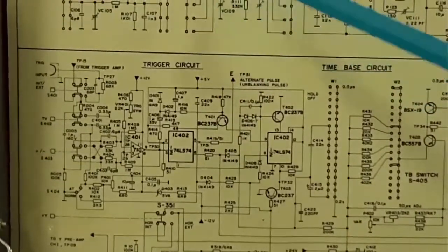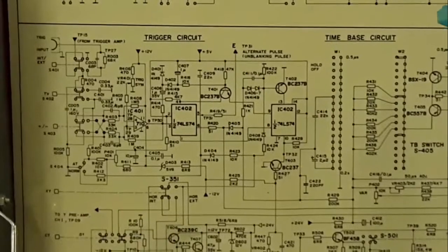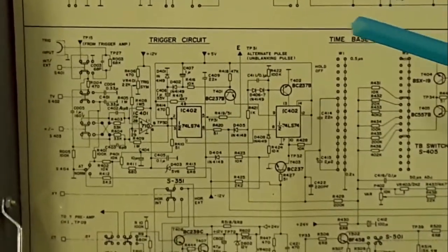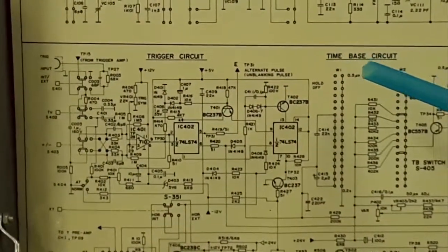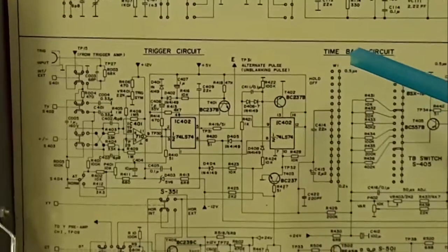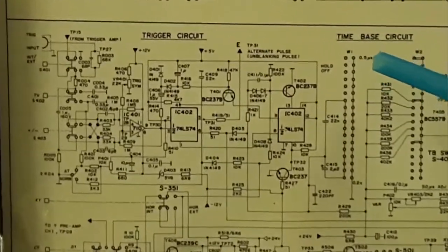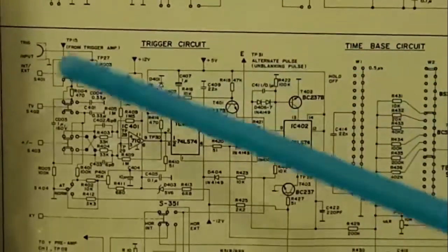Now, if you look at the trigger circuitry available in the CRO, a very big circuit is available. And what is the role of this very big circuit? Schmitt trigger is one part of the trigger circuitry, that is used to show any other signal in terms of a square wave. Because if you look at the definition of the Schmitt trigger, any irregular shaped signal can be converted into a regular shape, and that's why the Schmitt trigger is one part of the trigger circuitry in the CRO.